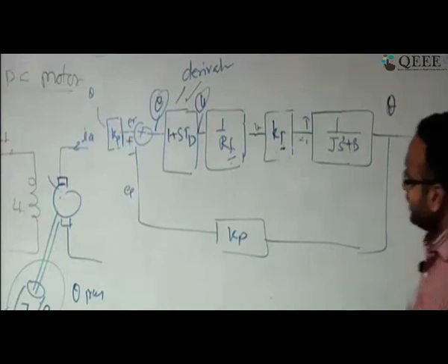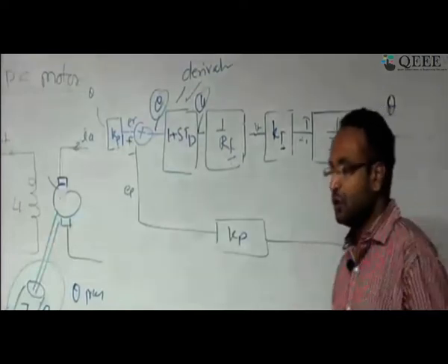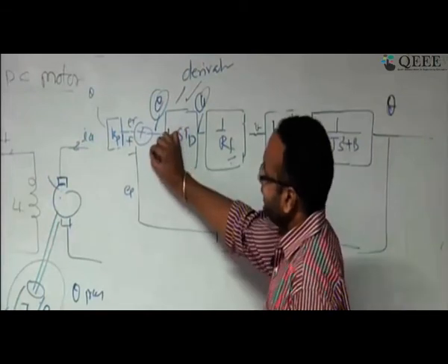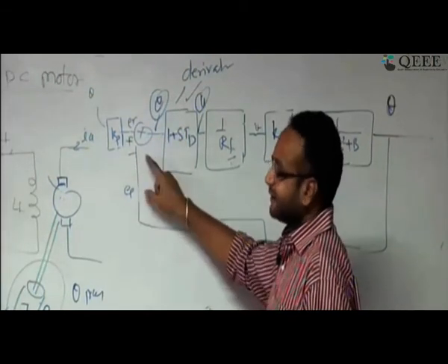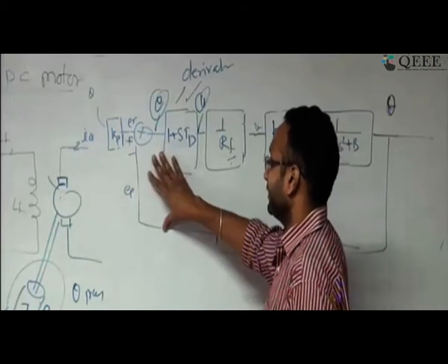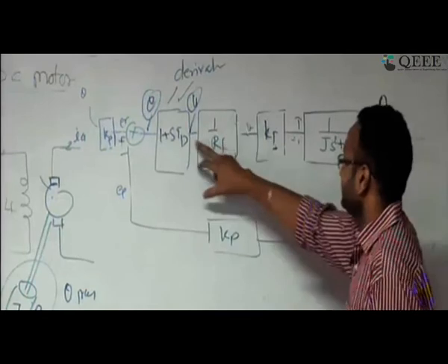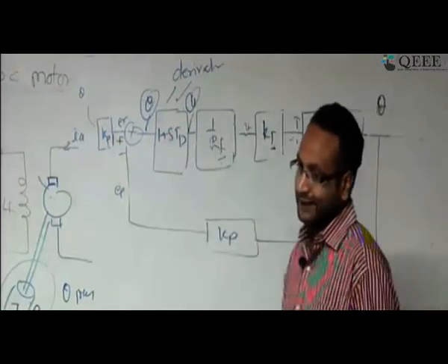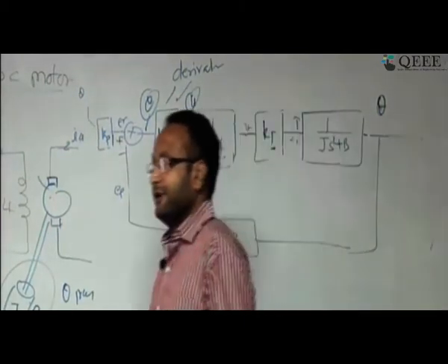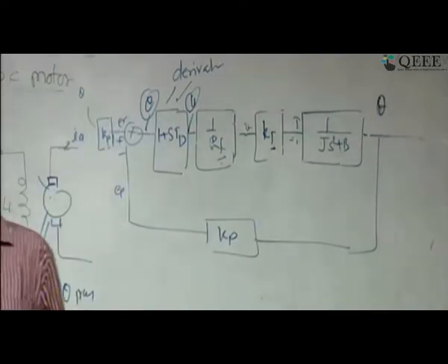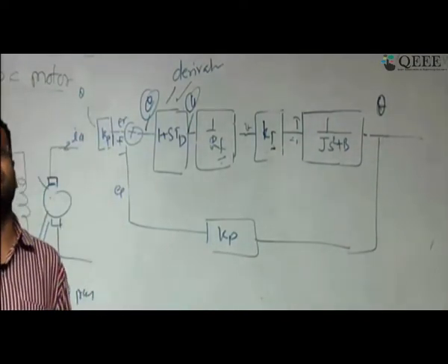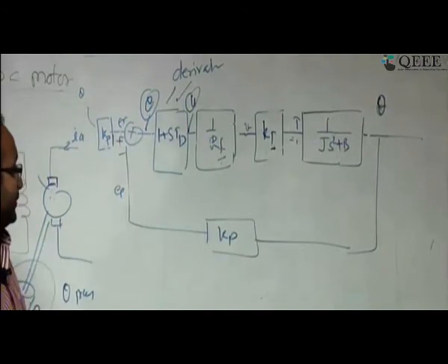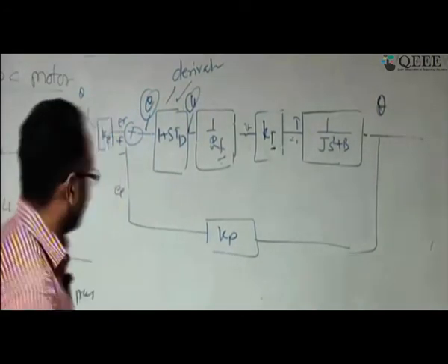Okay. So as I mentioned, by adding this derivative controller, you are making your system fast. But one problem one has to worry about is that if a small noise or some spike enters, the derivative of the noise term will get amplified, and once it enters, it is going to spoil your entire system, because a very high amplitude will cause damage. So intuitively, the derivative controller is good, because it tells you whether the error is increasing or decreasing, but I can't apply it here as is. So how do I do it? Some solutions people have worked out, and I wanted to show this in this case.